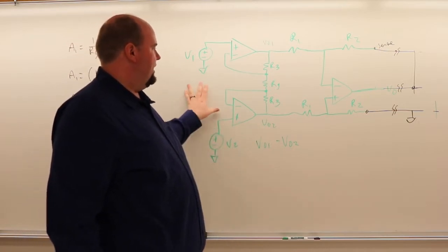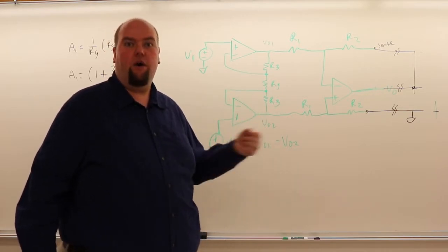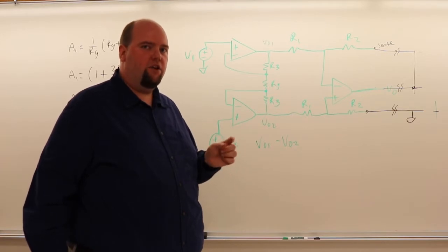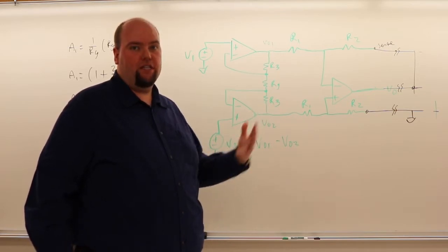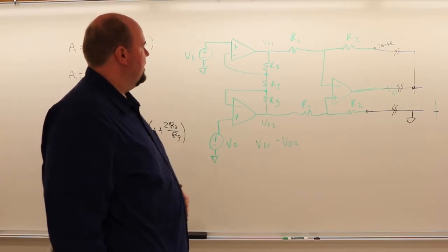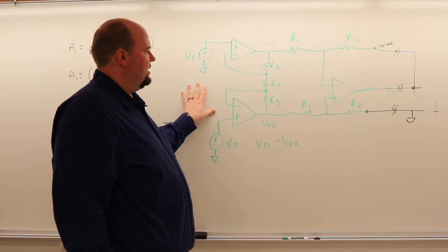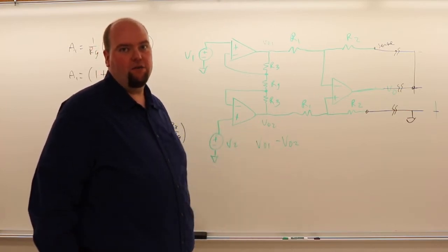Also, by doing different techniques like using coaxial cables or by twisting pairs, we can help minimize the noise that's created between two signals, but it's very difficult to minimize noise created in both of those signals as they travel a long distance, right? So in cases where there's a long wire, we can use this type of configuration to essentially subtract out the noise that's produced in a reference signal from our actual desired signal.